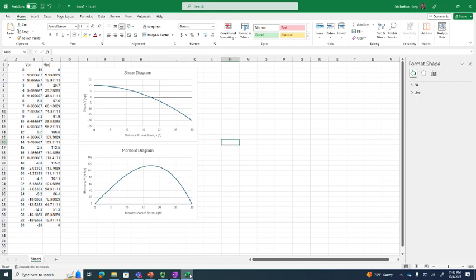And it's not. It's interesting, isn't it? It's not 20. I'm going to show you why here in a second. But I propose to you that distance is correct because look, where the shear diagram is 0, the moment diagram is maximized. Very interesting. What is the maximum moment that we're getting on our moment diagram? What is this? 115-ish? Is everybody kind of seeing that?